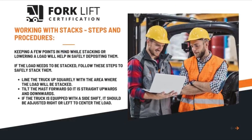Working with stacks, steps, and procedures. Keeping a few points in mind while stacking or lowering a load will help in safely depositing them. If the load needs to be stacked, follow these steps to safely stack them. Line the truck up squarely with the area where the load will be stacked. Tilt the mast forward so it is straight upwards and downwards.